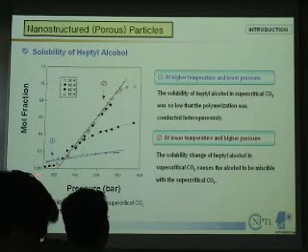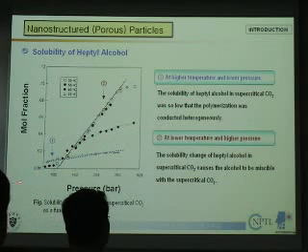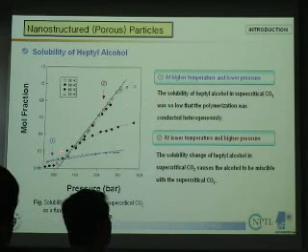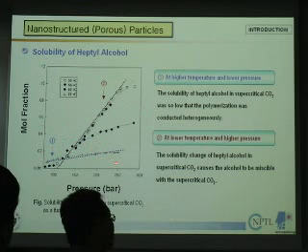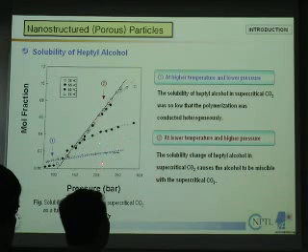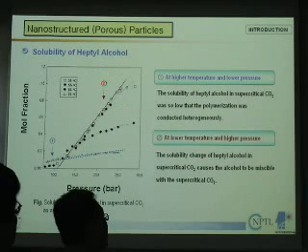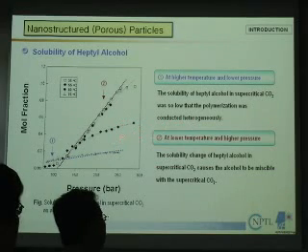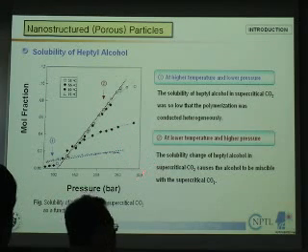And during the reaction, you need to have some kind of solvent or byproduct exchange process. You simply adjust the pressure, like this number 2: reduce the temperature and increase the pressure. Now the solubility of this heptyl alcohol in the supercritical fluid is very good. That means now this supercritical fluid can penetrate into the growing polymer particles,